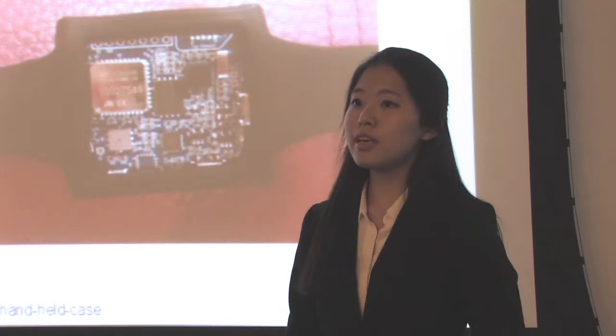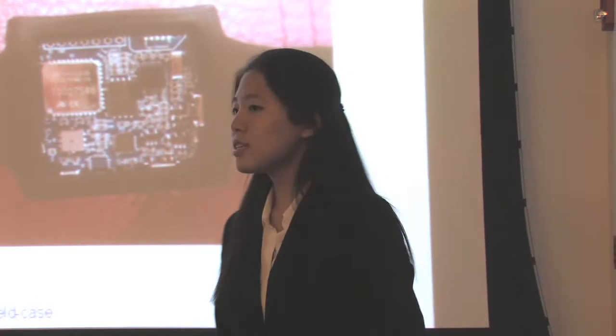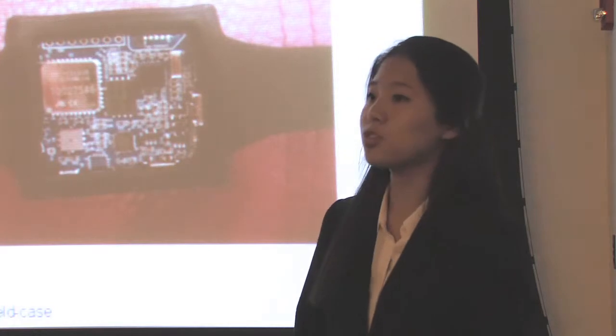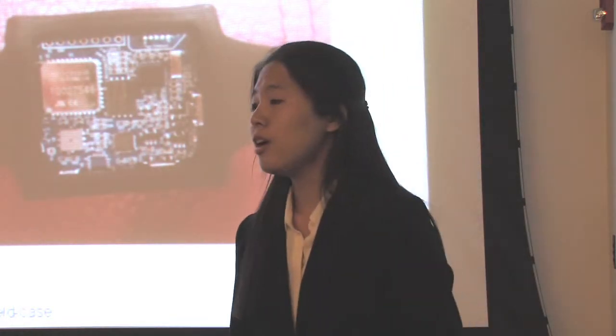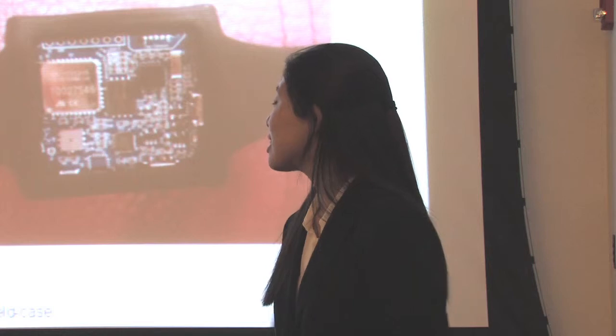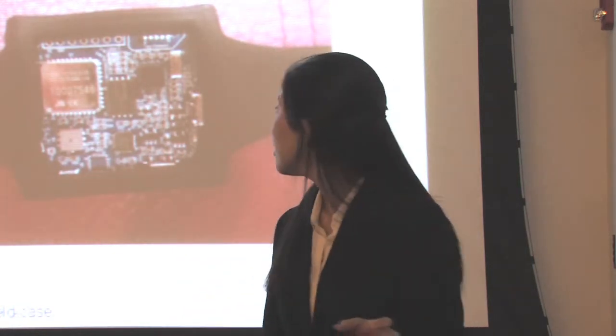The second is that the YEI sensor only allows us to record data in quaternion numbers. Meanwhile, InvenSense gives us a wide variety of different recording data. For this experiment, we decided to use quaternion numbers and Euler angles. The third difference is that the YEI sensor has a tare button on the interface of the PC, where whatever direction we're holding the sensor, if we click tare, it will orient itself to that axis. Meanwhile, the InvenSense has no such application on the Android. Therefore, we just had to assume that it was being oriented to the Earth's magnetic field.